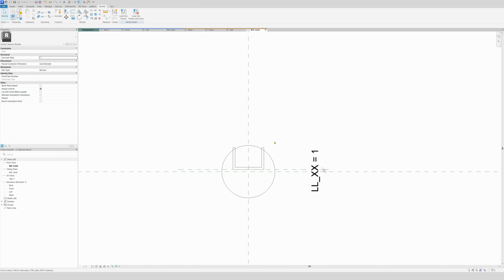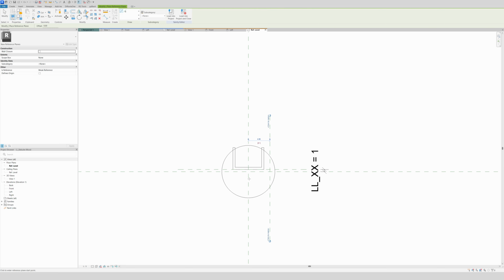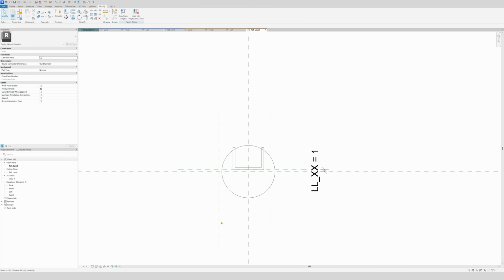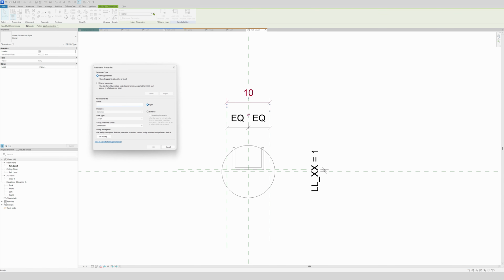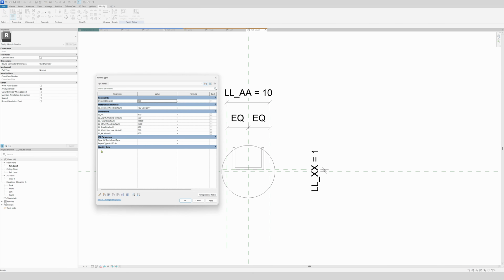And now for the voids, I will use some reference planes right here, right here. Also get them equally done. Voila, and this will be AA, and we will give it the same width. So we can the same width of the structure. So we're gonna copy it, Control C, Control V, oh, and voila. Oh, I took the wrong one. My bad.